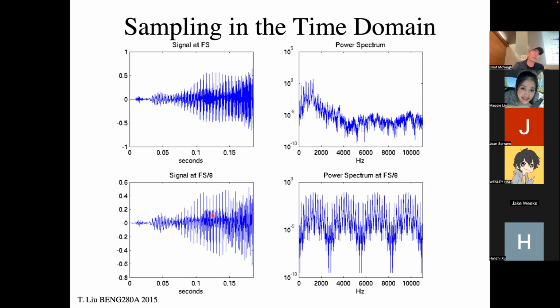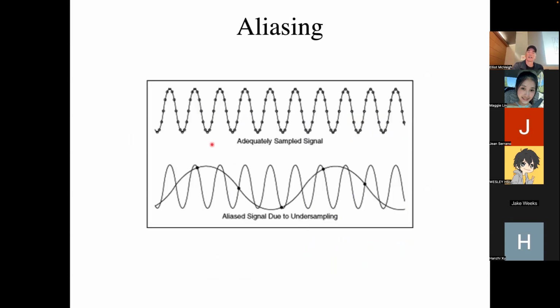However, if there are high frequencies in here that we have missed because we've undersampled it, those high frequencies will alias back into this estimate, right? And your spectrum is distorted. And we'll do an example of that. And that's called aliasing.